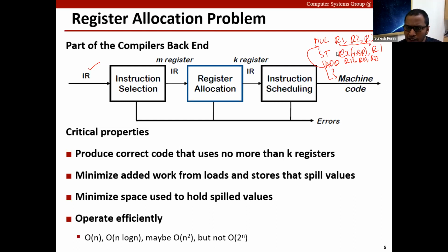Then by the time the processor hits the store instruction, the value produced by the multiply instruction is available in register R1, and the store can be initiated without putting the processor in a wait state.